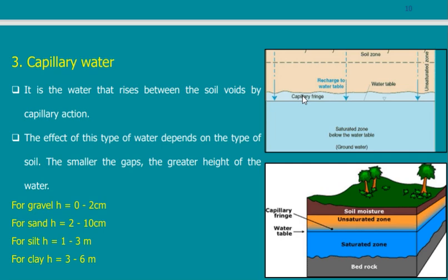If you are following me, you can answer my next question. If I excavate ground in a certain location and there is a groundwater level, and then water returns again, to which level will it return? To the capillary rise level or to the groundwater level? This is the groundwater table, and above it there is still this yellow fringe. This yellow fringe is called the capillary fringe, where water can climb through the voids and reach this.